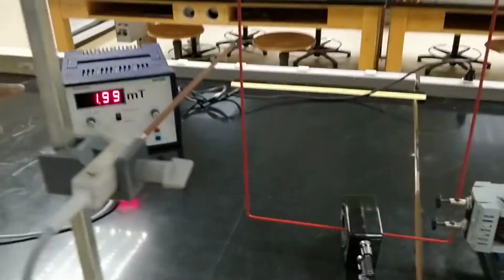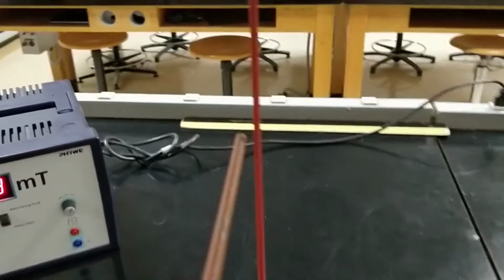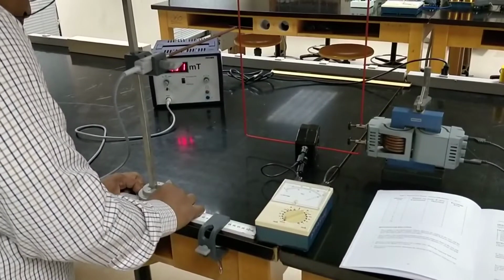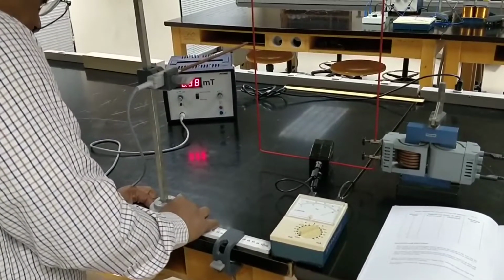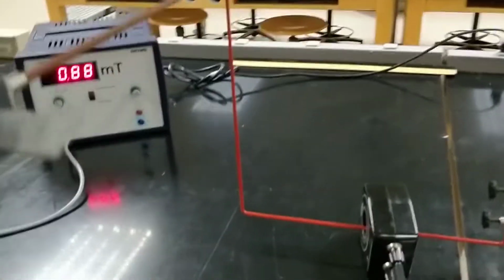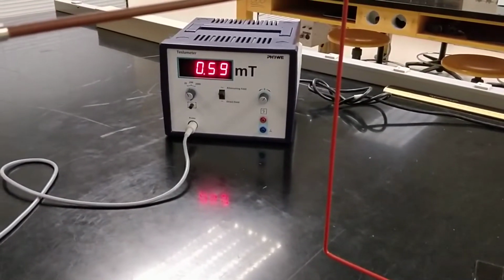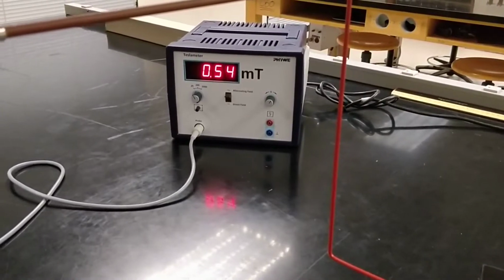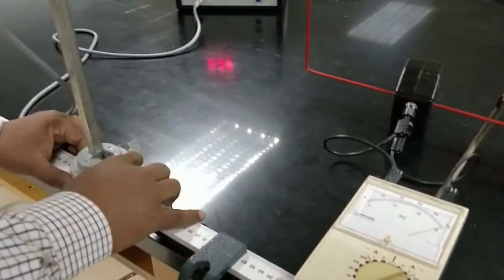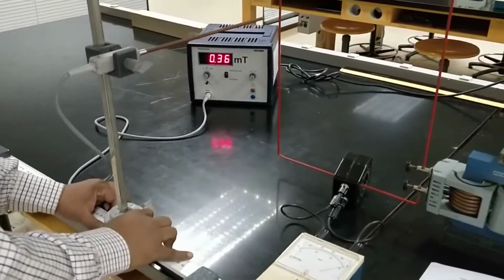So for 1 centimeter we are getting 2 milliteslas, we said, or 1.98 milliteslas, and then I will go now 1 centimeter from that. Okay, so I will be moving 1 centimeter, so this is 2 centimeters if you want to, and this is 0.9 millitesla or 0.89 millitesla, and this is 3 centimeters, so I'm getting 0.54 millitesla. This is 4 centimeters, and I am getting 0.37 millitesla,